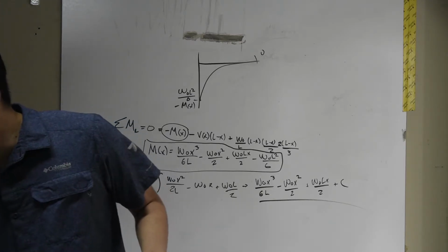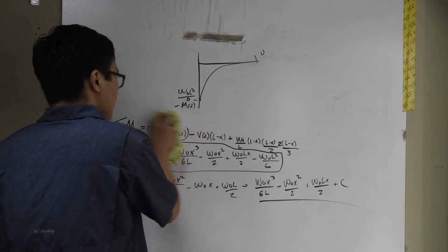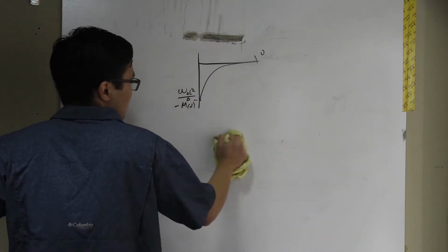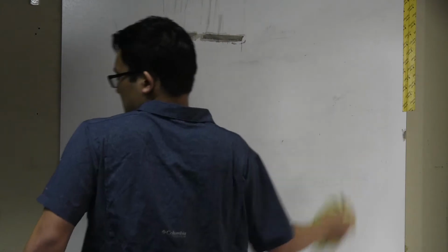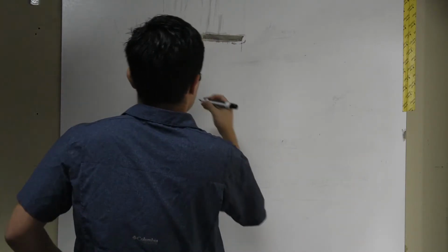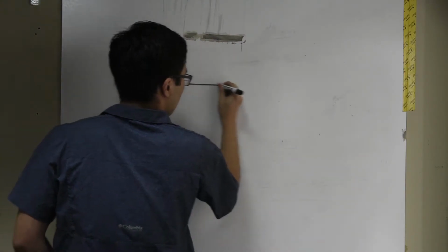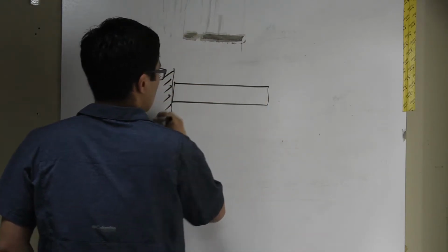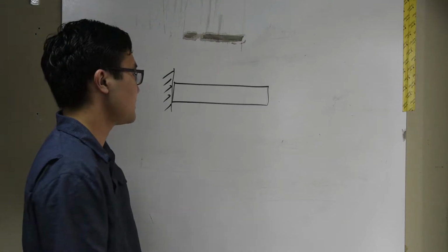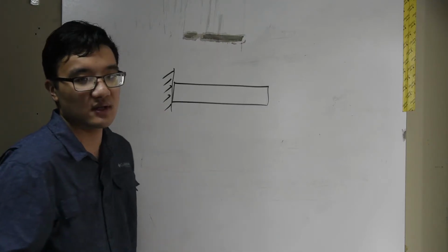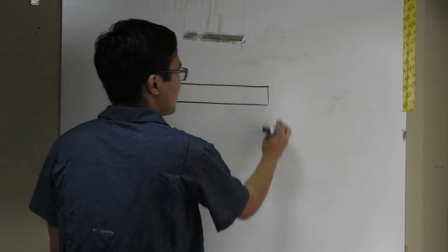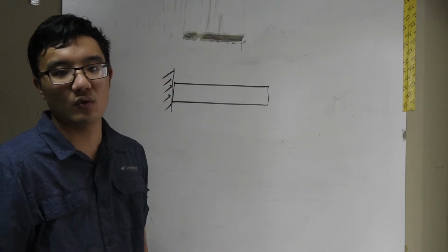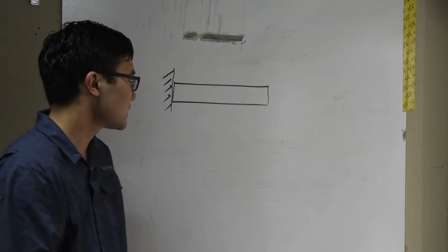Okay, so let's go ahead and talk about a few more cases real fast, just so you guys aren't super confused if something like this happens. Now I always do the cantilever beam, but again, this just has a unique set of boundary conditions. I know this free end has to be 0 for shear and for moment, and at the wall it has to equal Ry or has to equal M.